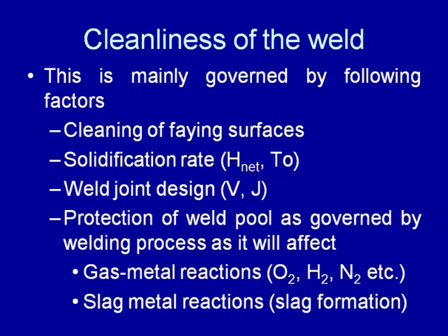This solidification rate will be governed by the heat input and the initial plate temperature. Higher heat input and higher preheating will increase the solidification time and will reduce these inclusions and the gas entrapment tendency in the weld metal, thus producing a cleaner weld.